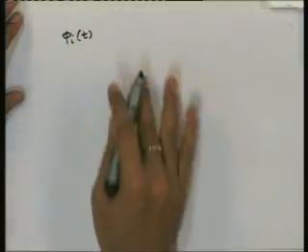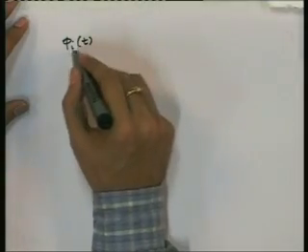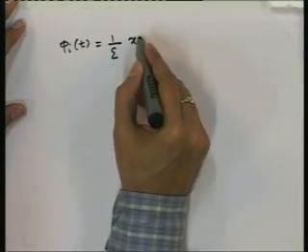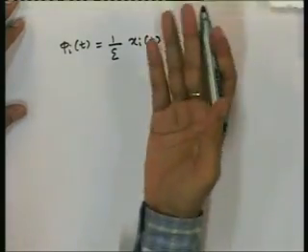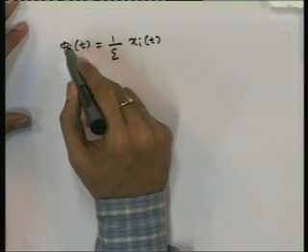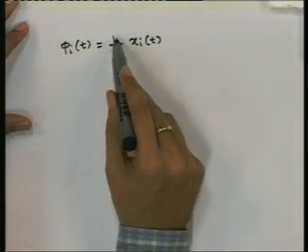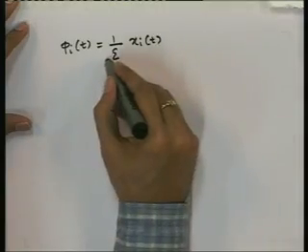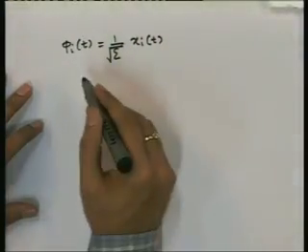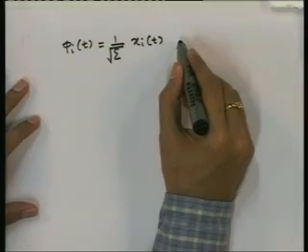So, we can say that phi_i(t) we will generate so that they are orthonormal. So, phi_i(t) can be taken as 1 by root E times x_i(t), given that we have constructed x_m(t) basically. So, for the i-th vector here, the orthonormal vector, we just divide by this, which is root E, so that the length of this is 1 and they remain orthogonal. If you scale, they remain orthogonal.